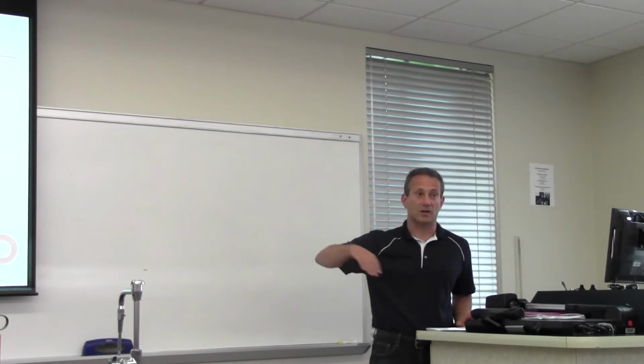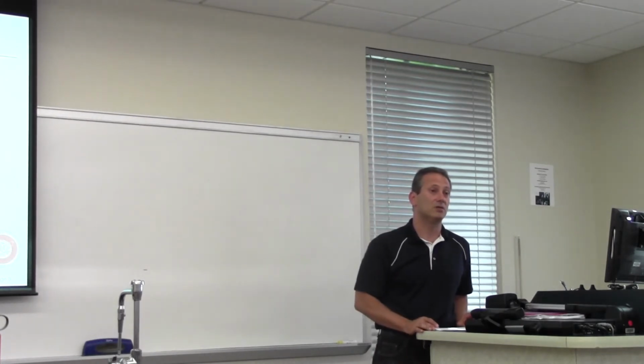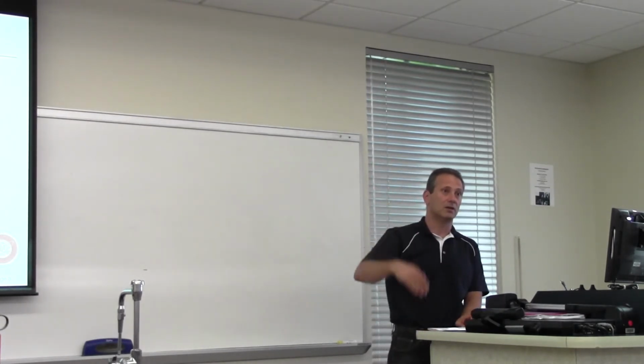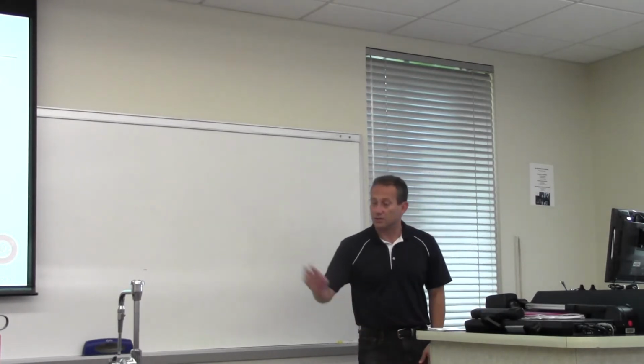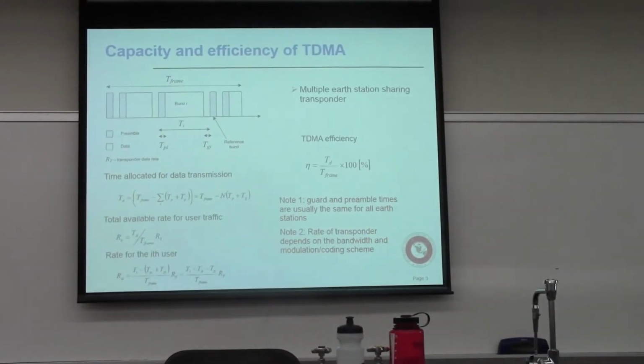Especially not for the large backhaul TDMA satellites. You may do it for LEO when you talk directly to a phone, but that's a different story. Here the coding is much lighter because the channel is much easier to deal with than the Rayleigh fading channel that we have in terrestrial networks.